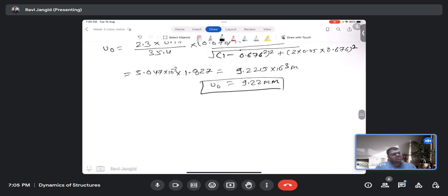Let us suppose the mass is fixed at the center. I was thinking it should be a fan or motor at the center of the pivotal point. So the motor mass is 28.5. Then there are some sort of blades. My motor is attached with some sort of blades, where each blade mass is 2.3 kg. These are symmetric, but if one blade falls down, it will create the unbalance. If that blade does not fall down, then it is a balanced mass.